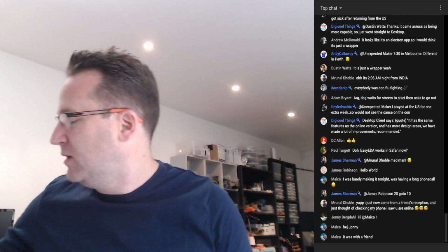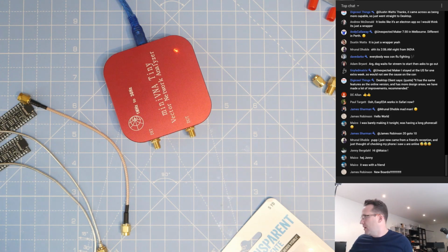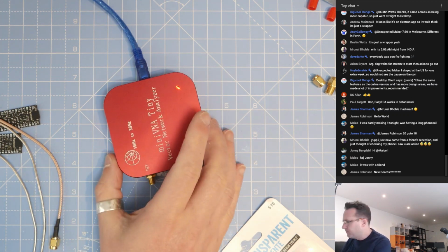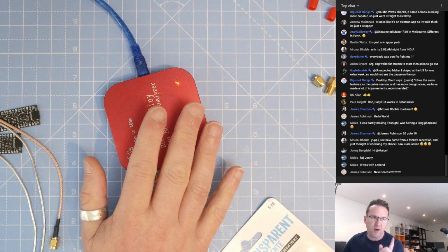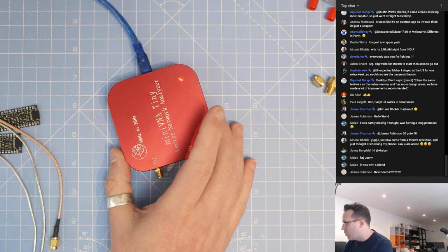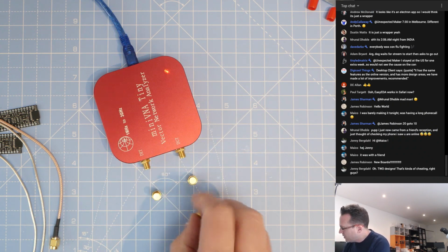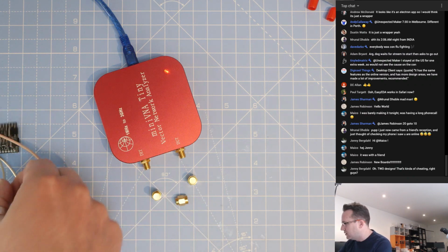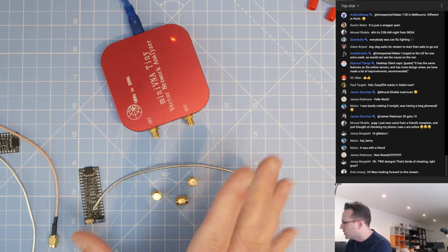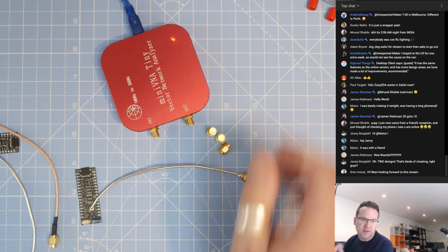Before we jump into the VNA, my VNA is currently plugged in, but it needs to warm up. Remember, for those of you that caught my stream a couple of weeks ago, I need to recalibrate. You're supposed to calibrate before every session, but I need to recalibrate anyway, because it was brought up to me that I was calibrating with my little terminators, which is a very short length, but then I was using these long coax cables for my testing. So obviously my transmission line was wrong compared to my calibration, which is going to give me off results.